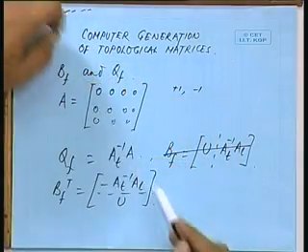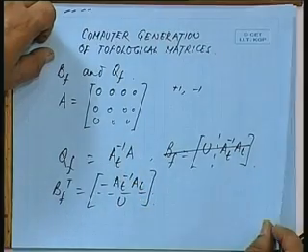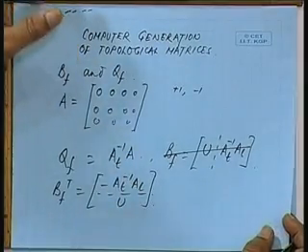So, computation of this will require computation of A transpose inverse. Now, if you are having say a 50 or 60 node system, then it is not advisable to go for the inversion of such a matrix, because A transpose will have the dimension 50 by 50 or 60 by 60. All right. So, if A transpose